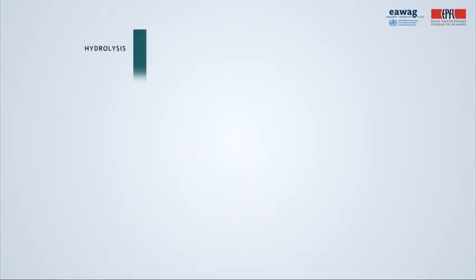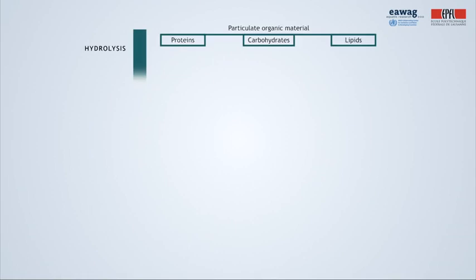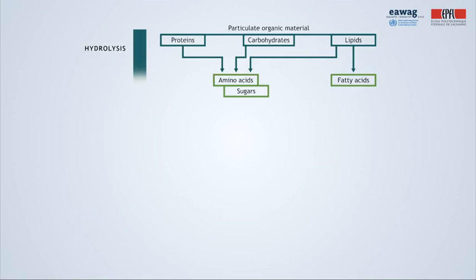Now let's look at the biochemical processes. Anaerobic digestion happens in 4 steps, although these processes happen partly simultaneously. The first step is hydrolysis. It is the slowest of the 4 degradation steps. Bacteria transform complex organic materials into liquefied monomers and polymers.